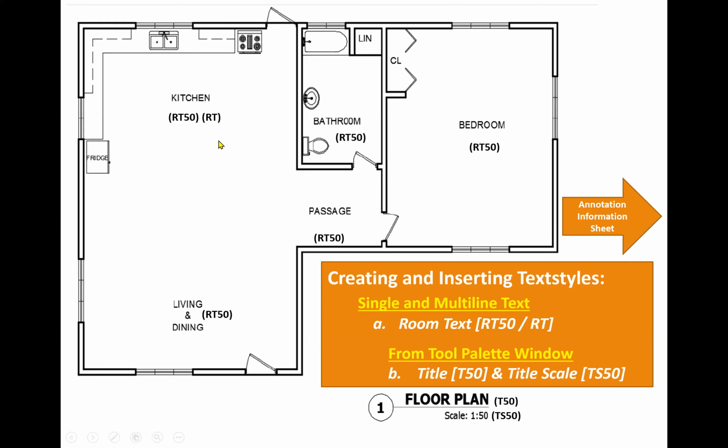You're not going to have floor plans with scales 1 in 200 and 1 in 10 and those. No. It's usually residentials are mostly 1 in 50. And those large commercial drawings, you may have those going up to 1 in 100. Okay? Because it will be too large to print on a paper if it prints at 1 in 50. So you might have to choose a different scale so that it makes the drawing smaller.